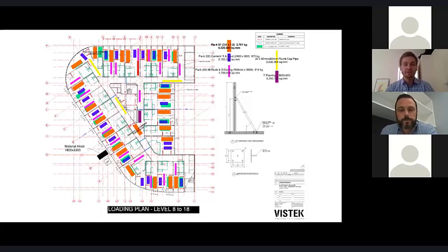Yeah, we'll certainly quite often look at that option, every second wall being load bearing for different arrangements, particularly for hotels. And it's something that probably needs a bit more thought early on, just in terms of the cost and implications of that, because it's very easy to overlook the benefits on site, I guess, when you've got 2 costs, and the material cost is more significant when you're not just loading every party wall.